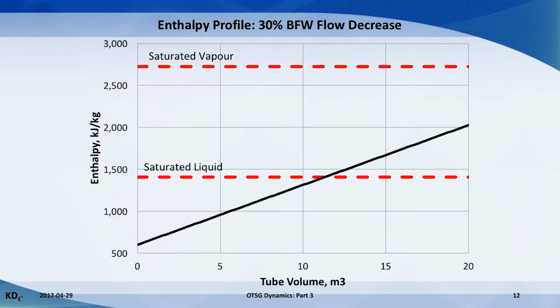The next transition is a sudden decrease in the boiler feed water flow rate. This could be caused by a sudden drop in the feed water supply pressure caused by shutting down one of the high-pressure pumps. The response that we see is a sudden increase in the measured steam quality, but the level in the steam separator drops slowly. How do we explain both observations, and does a sudden water shortage cause a problem?